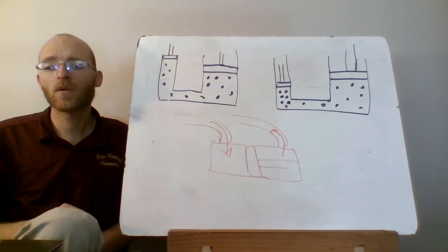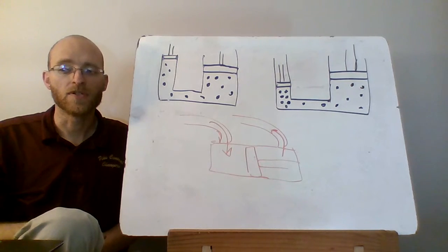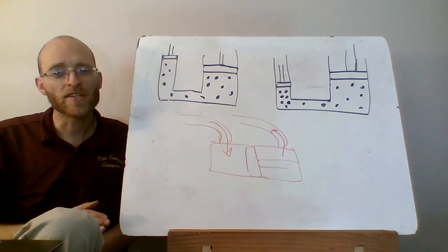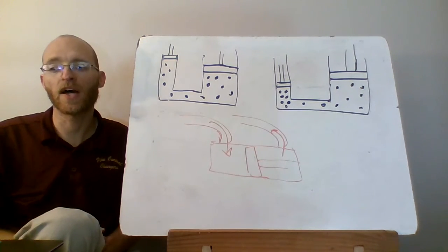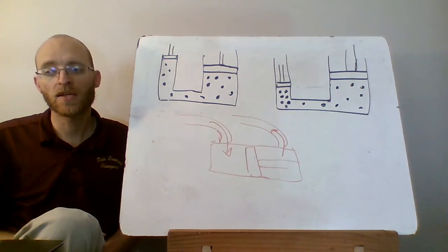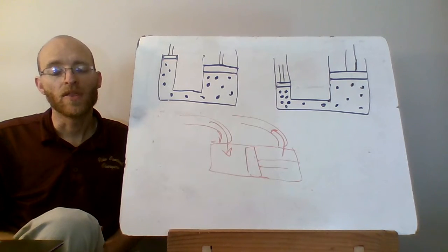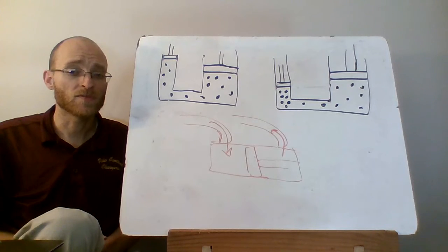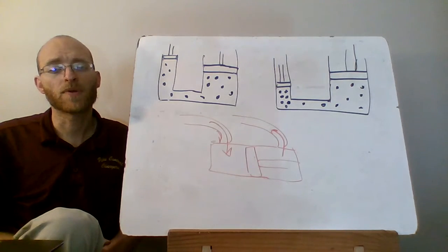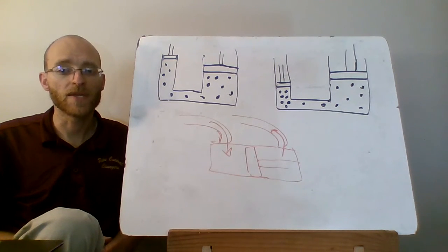So it's a lot quicker, but it also creates jumpier motion. Not quite as precise, probably because it's faster and jumpier. You can't quite control it as well. They do have to be lubricated, but they're generally cleaner than hydraulics, but also generally produce less power. They're typically operating around 100 psi.